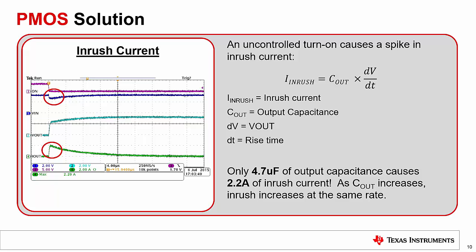As a result, the power supply cannot handle the load and must drop its voltage to compensate. This inrush current can lead to undesired system performance, such as a reset or damage to external connectors or PCB traces.